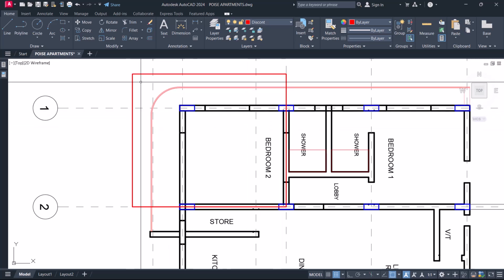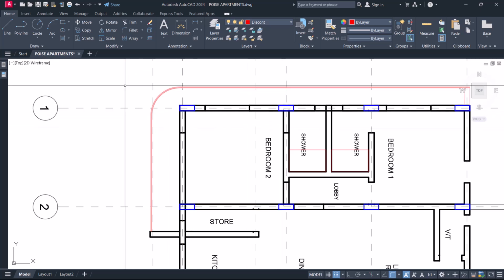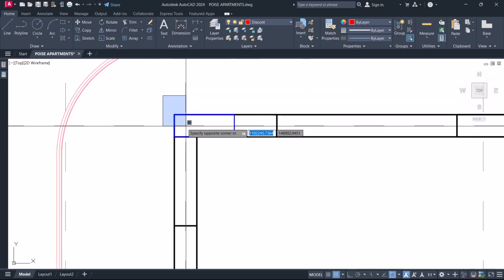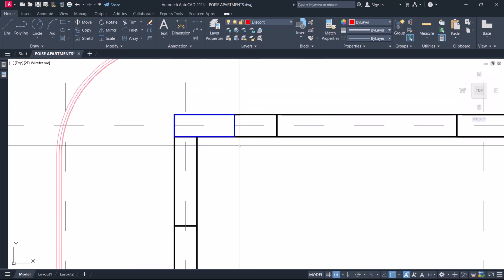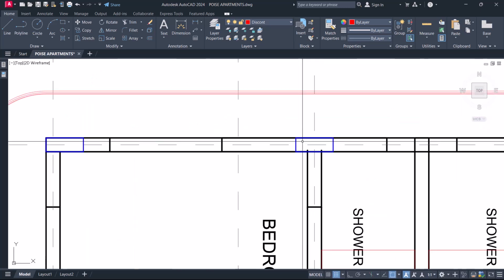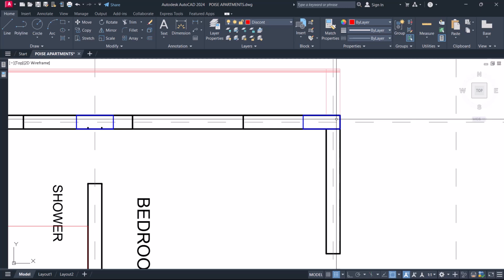Okay, and like I said earlier, when you are designing a flat slab, moment transfer is easier when you have columns somewhere at the center of your slab. Or let's rephrase and say, moment transfer is easier when columns are at the centers of your slab, against the ones that are at the edges, like this other one.